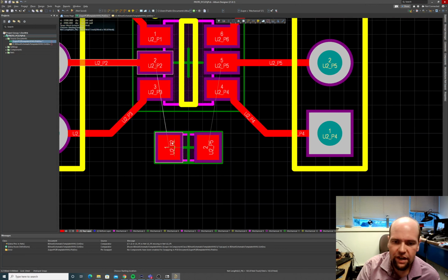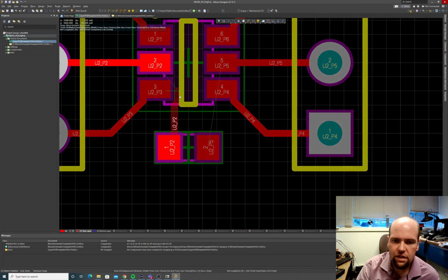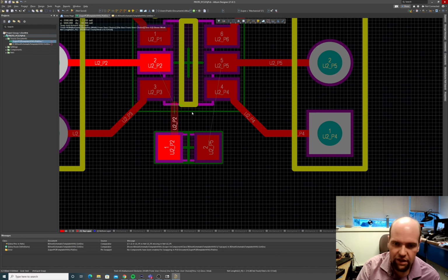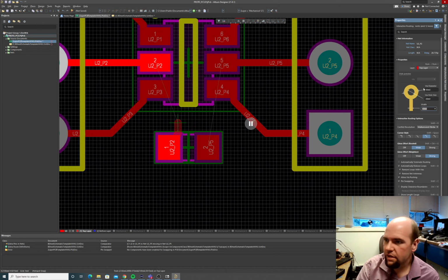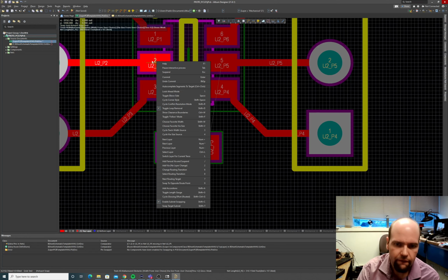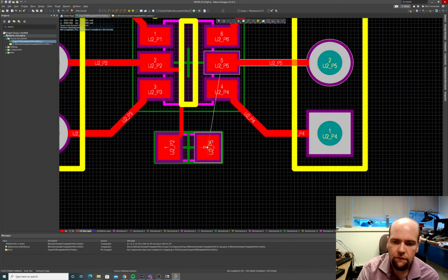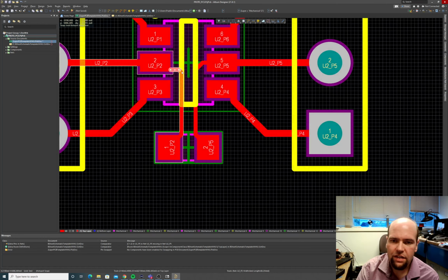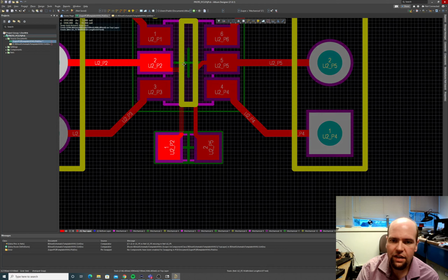Okay, now moving that capacitor down there, now what I can do is, if I want, set my grid really tiny and set this to 6 mil. And sneak this in here. And some people don't like to have exits that look like that.